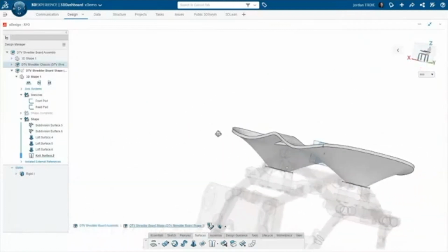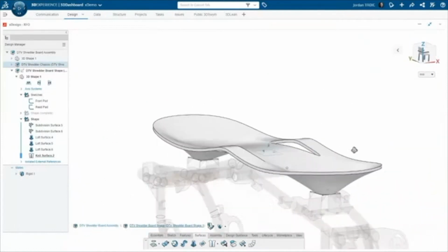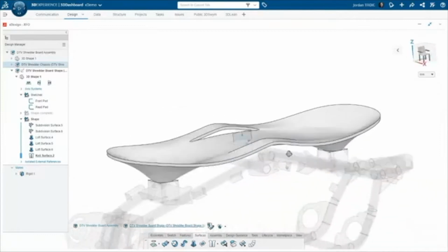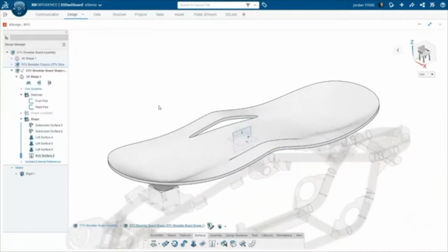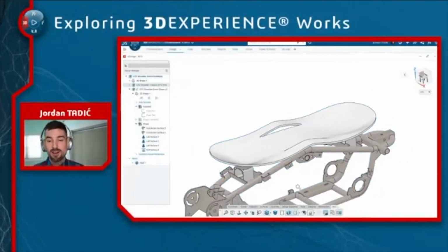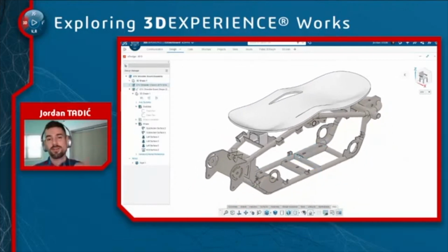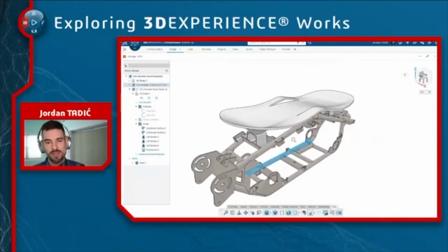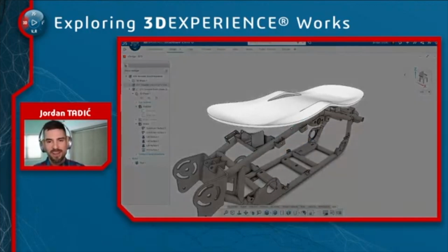And again, I think this is a really cool workflow, because not only did we use sub-D modeling, kind of like a surface modeling thing, where we grew the model out and merged things together, but we also used surface modeling features with it: the loft feature, the knit feature, the make solid option, and it all comes together. And if I were to edit either one of those sub-D models, all the downstream features would update very predictably. As far as workflows go on the 3D Experience platform, there are so many that you could do, merging all these apps and jumping between them and using all the different features they have to provide. Pretty cool stuff.